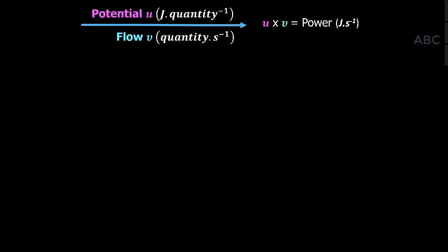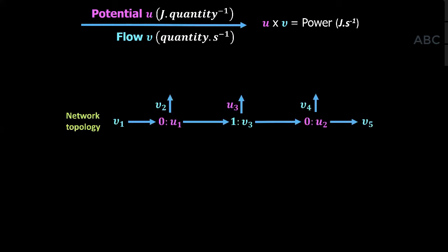So now let's get down to the guts of what bond graphs does. We're starting with this idea of transmission, and that transmission always has two adjoint variables. It's got a potential, which is the driving force, driving potential, and it's got a flow, and their product is power. But now we've got to think about the network topology, and then we've got to think about storage and dissipation. So first of all, network topology, and I'll give you examples of this in a minute.